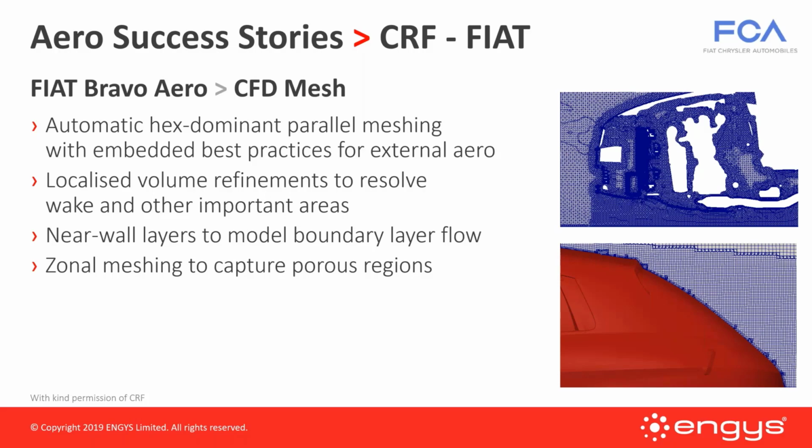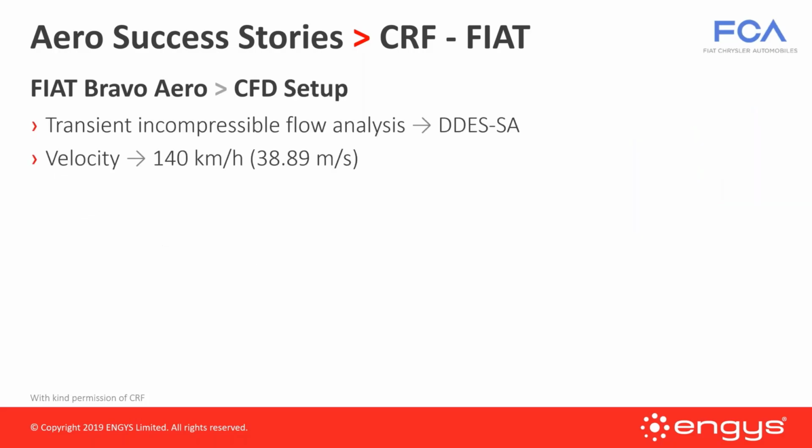There's always layers on specific components. There's always volume refinement boxes. These are scaled to different sizes based on the vehicle size and type. And then there's also zonal meshing to capture porous media.